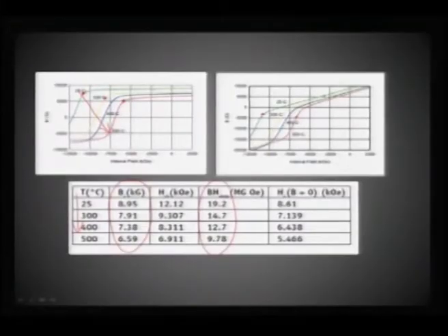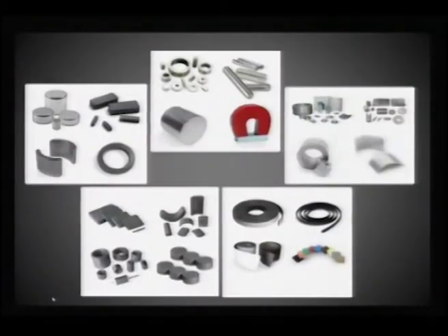application. So, you can use these permanent magnets in a variety of environments, and this is another view graph just to tell you where all these permanent magnets are used. This is the neodymium iron boride, and this is aluminum cobalt nickel, called alnico. This is another permanent magnet, and these are ceramic magnets usually made of ferrites, and this is your samarium cobalt magnet, and this one is a new generation magnet, which is nothing but a composite, called flexible magnets.